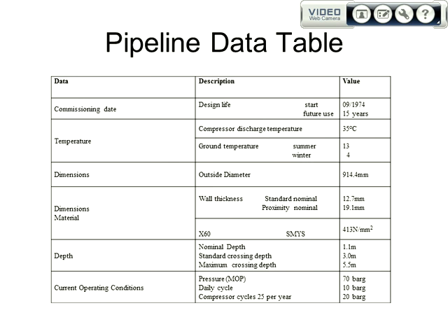Right, so are there any other questions on this that anybody wanted to ask? The current year is 2017, right? We are considering 2017 as the current year. Is it important we get information on the design life, the life it was designed for? Well, it doesn't really matter because the code has got an SN curve in it, which will then tell you how much fatigue damage you've accrued.